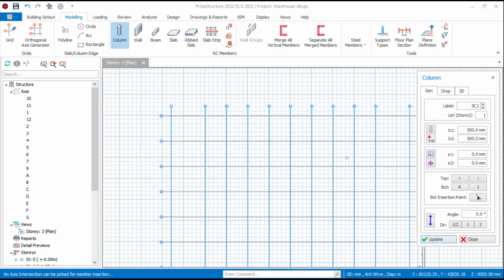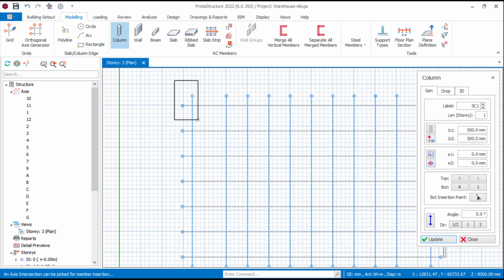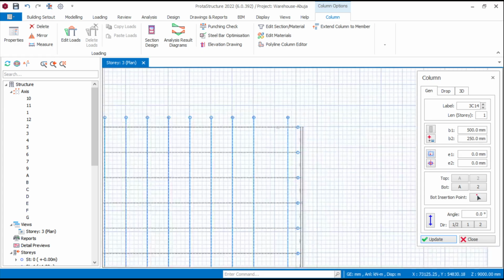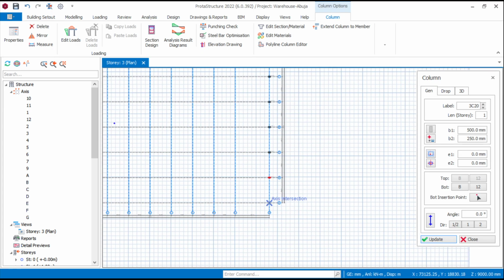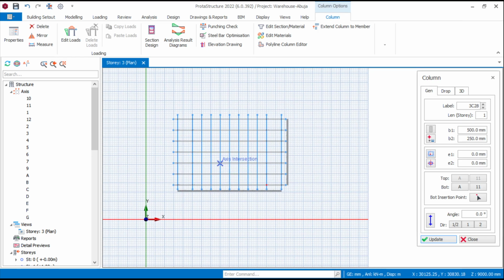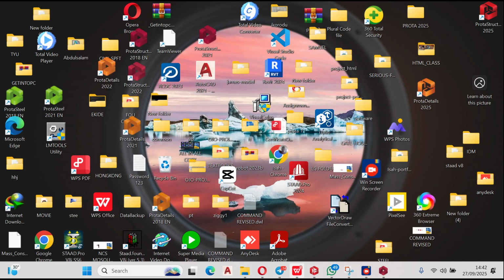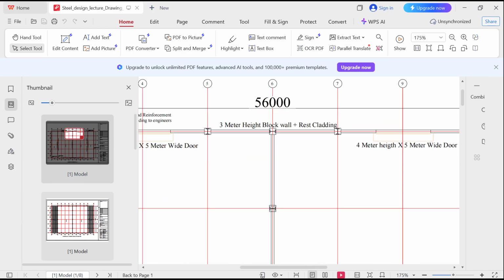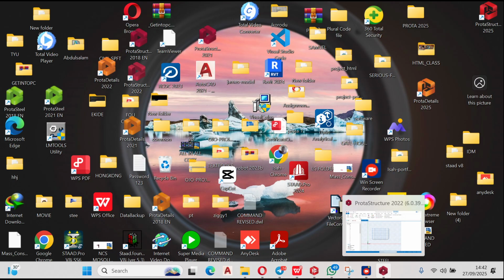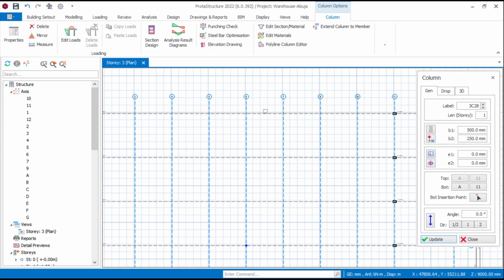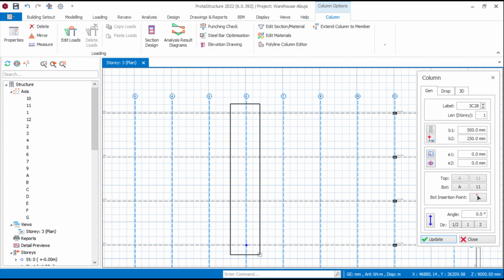Now when you check the architectural drawing, you'll see that we have stanchions in this place. We have stanchions here. We also have stanchions here. Are we together? We have stanchions here, and also here. Now, very good. Let's look at where we also have stanchions again. We have stanchions in green line 6. Anywhere you have a stanchion, there must be a column pedestal there. The load of the stanchion is transferred to the column pedestal, then the column pedestal transfers the load down to the foundation.